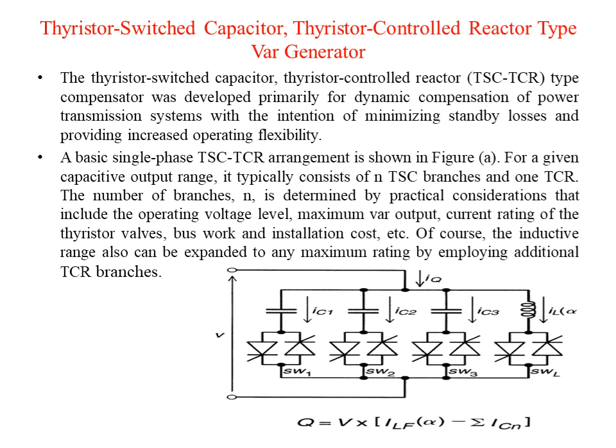Of course, the inductive range can also be expanded to any maximum rating by employing additional TCR branches. So there is flexibility to also increase TCR branches, but there was no flexibility to increase FC branches in case of FC-TCR.